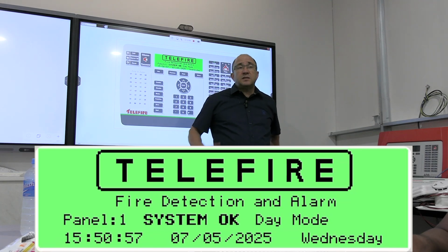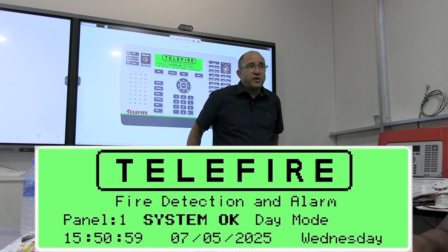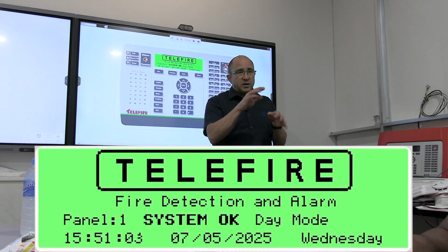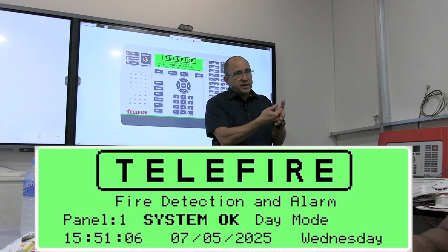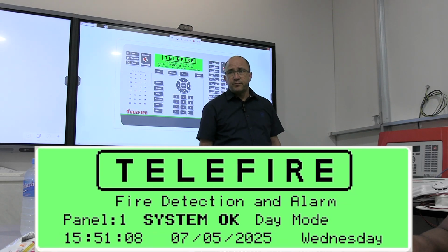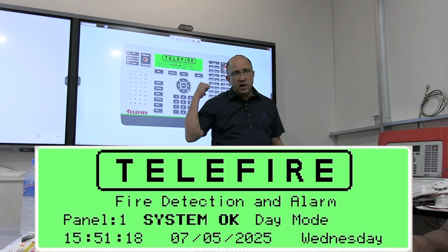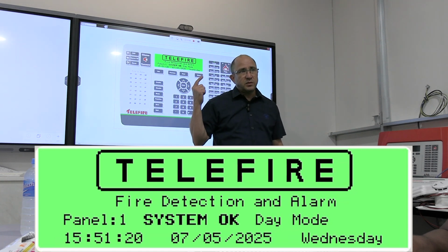In other words, if this is a meeting room and you have to do renovation, you take off the detector, you put it inside a nylon bag, you close it, and you write meeting room, or behind the detector, meeting room, if you have only one. When you take it, you must always put it back because it's addressable. Number 12 is written meeting room, so it's waiting for number 12 to go here.